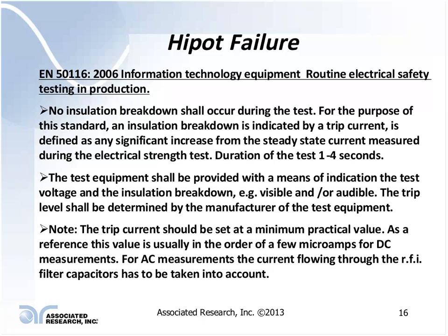I've had customers have products with problems, and the standard allowed them to set a much higher trip current, so they went to the maximum, but if they had set it to something a little higher than what the product normally would draw, they would have caught the defect immediately rather than 6 months down the line.